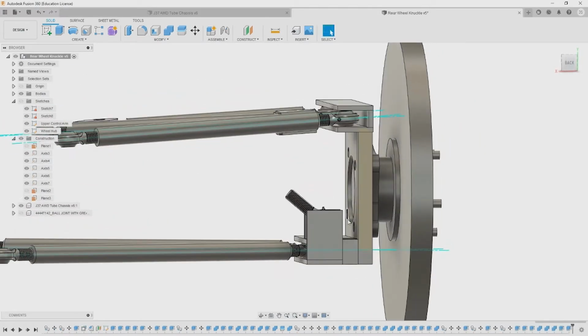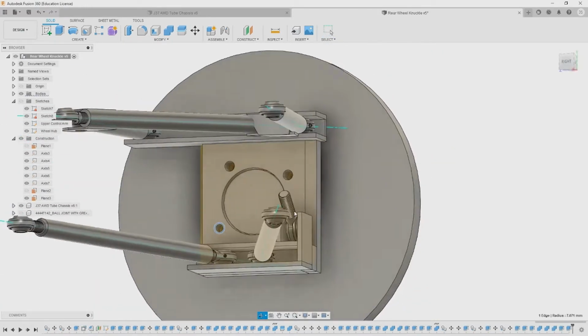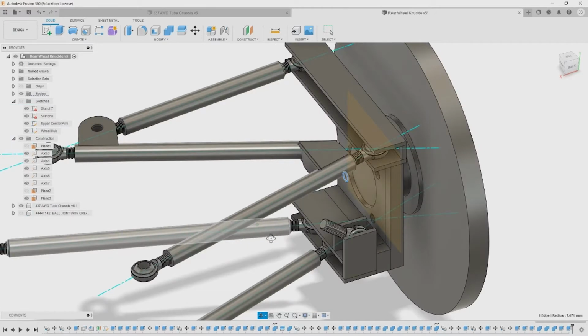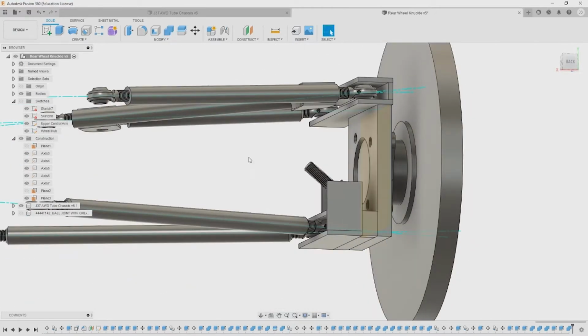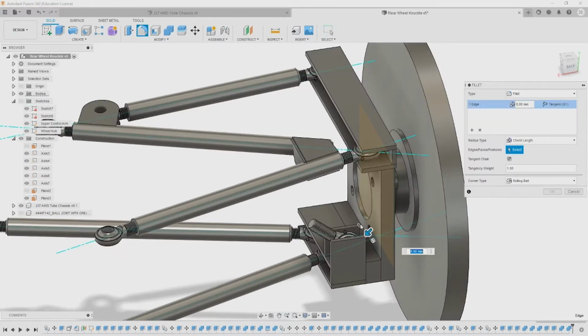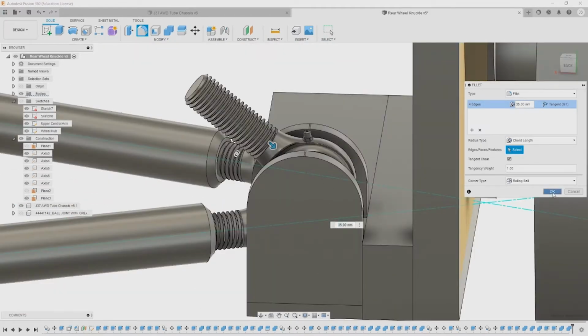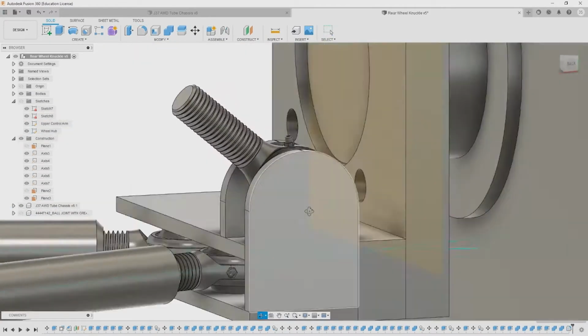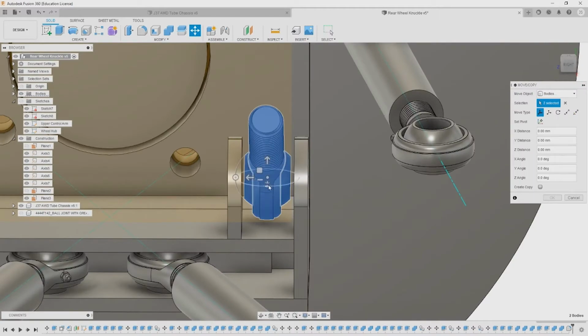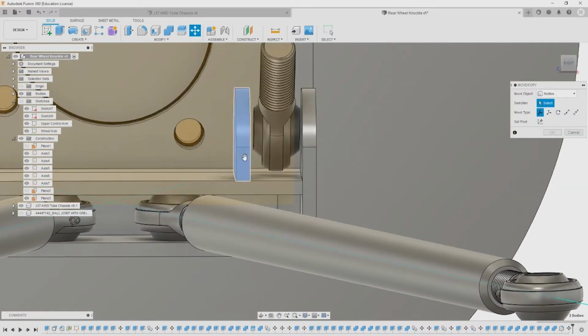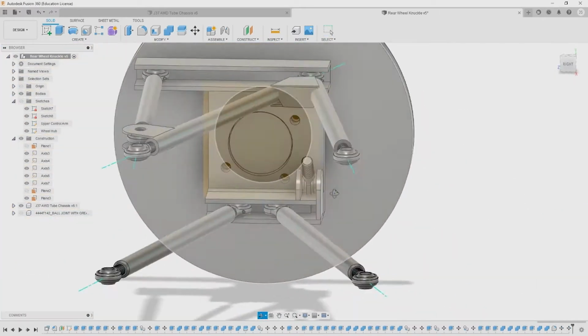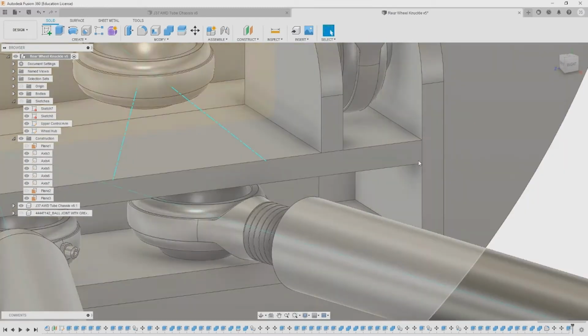Moving on, we're going to switch back over to the rear hub assembly. I really wanted this to become a flipped assembly from where it is right now, where the toe adjustment was actually in the back, and that would just help if there was any flex with that part, make a more ideal toe in a situation where you're exerting a lot of load on the car.